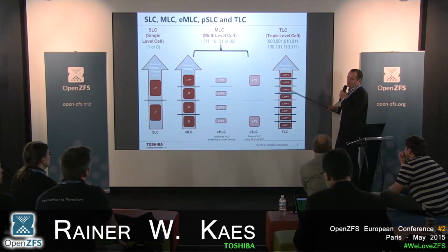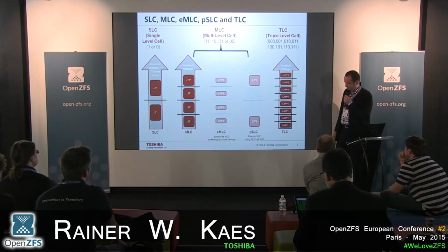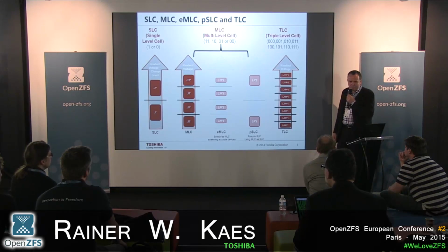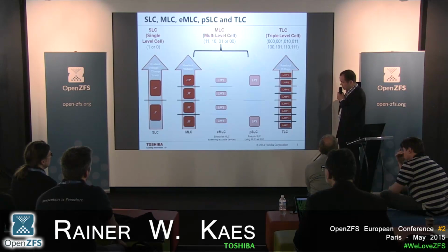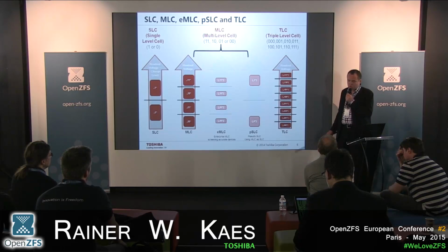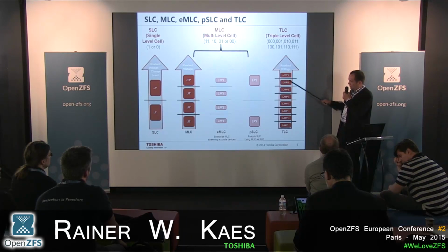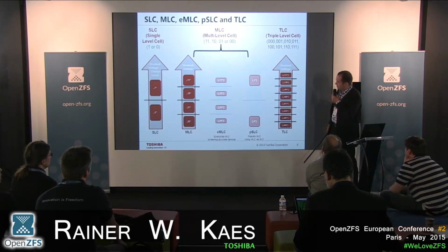This is why a triple level cell for client application still works, because we do not have to erase too much. For enterprise application, it needs very well managed error correction and a lot of over provisioning, meaning spare cells to mask out the cells that are so leaky that they go to the wrong value.